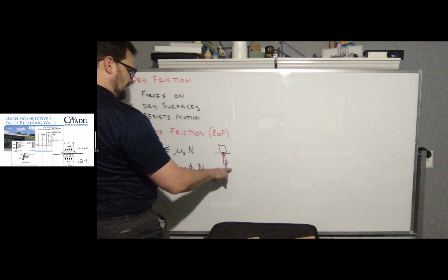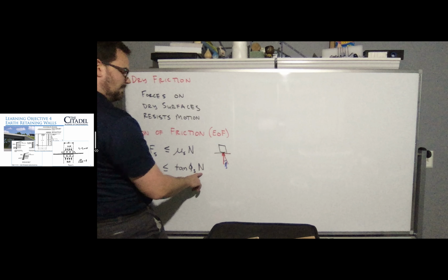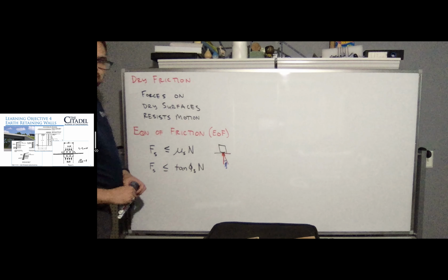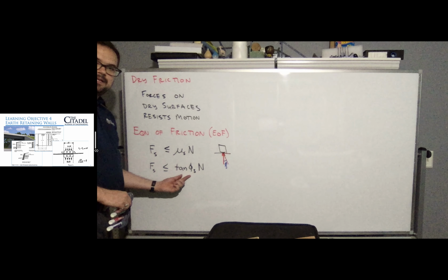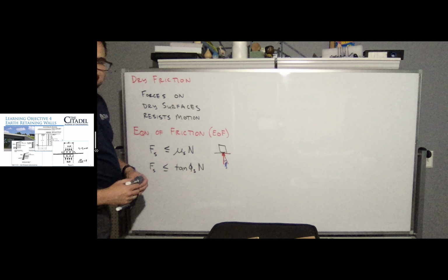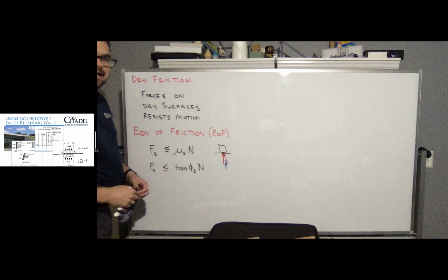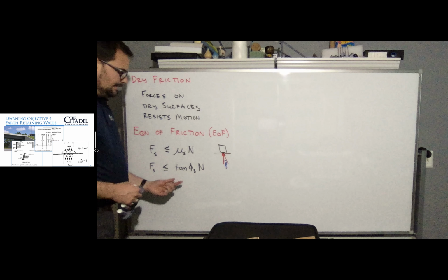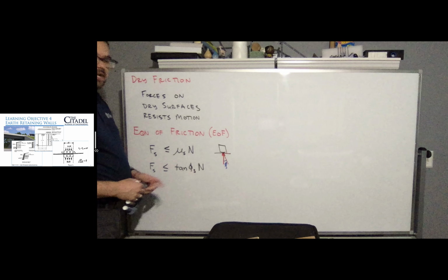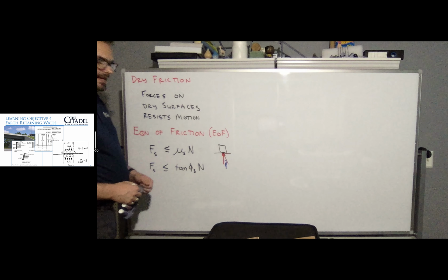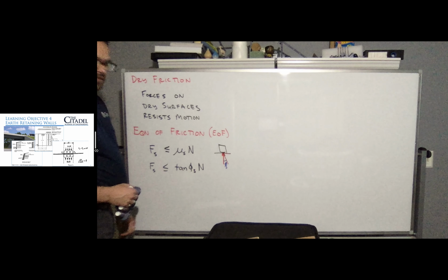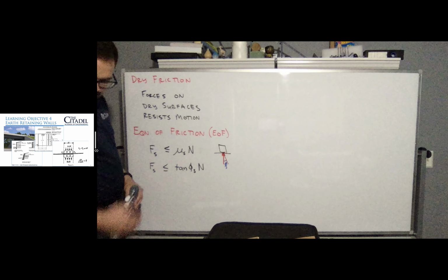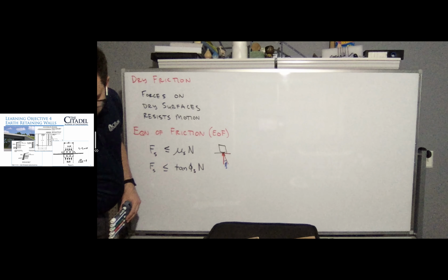And so we would look at that F sub s, the frictional force, divided by the normal force, is equal to the tangent. That tangent of phi is equal to the coefficient of friction. This tan phi concept gets used a lot in soil mechanics, where we'll talk about an internal friction angle. This is going all the way to your senior year, where you're looking at your geotech courses. Tan phi, an internal friction angle phi, is going to be used a lot when we do that. So it's this little angle in here, the friction angle, that describes the relationship between our friction force and our normal force. That's page 73 of your FE reference handbook.